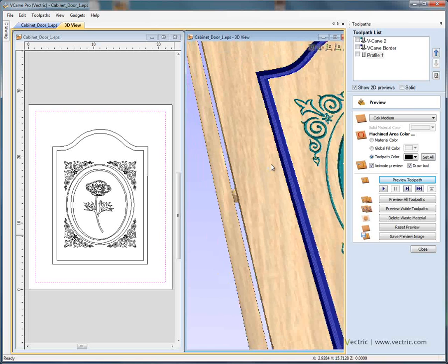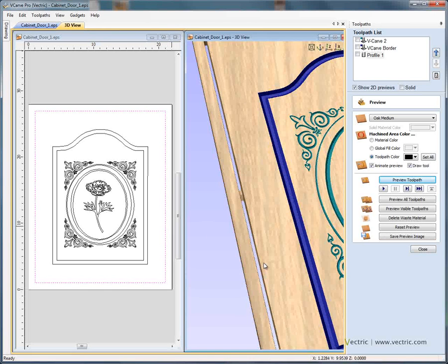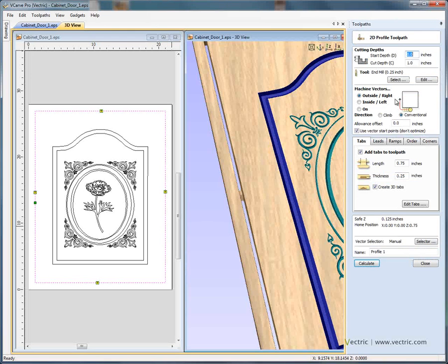Now this toolpath is going to plunge onto the edge of the rectangle down this vertical edge, so we might leave a witness mark. Ideally we want the cutter to start away from the panel, to lead in, profile around and then lead off at the end. So to do that, we say profile machine, we say okay, let's add leads. So add leads, let's make them circular leads, let's make them 1.5 inch radius, 1/2 inch long.